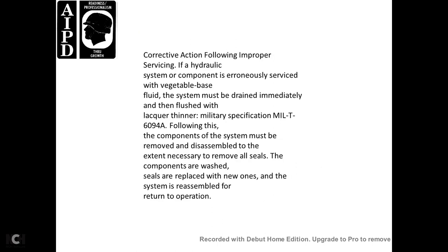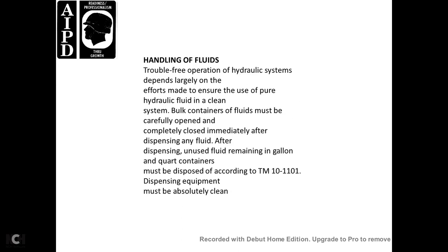Corrective action following improper servicing. If the hydraulic system or component is serviced with a vegetable-based fluid, the system must be drained immediately and flushed with lacquer thinner, military specification MIL-T-6094A. The following components of the system must be removed and disassembled to the extent necessary to remove all the seals, components, and wash seals and replace them with new ones. The system is then reassembled for return to operation.